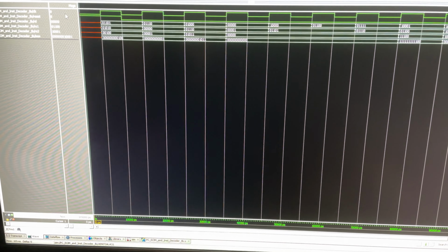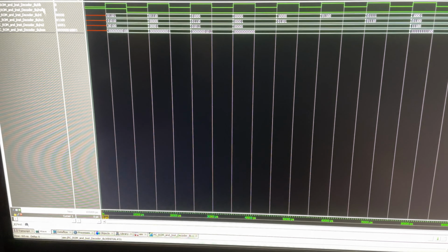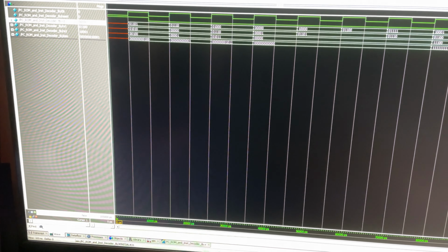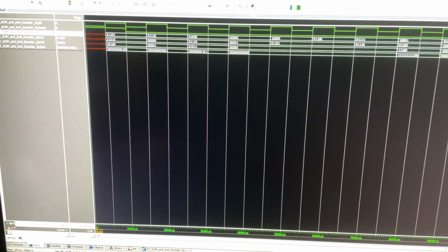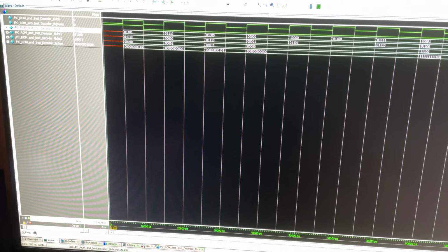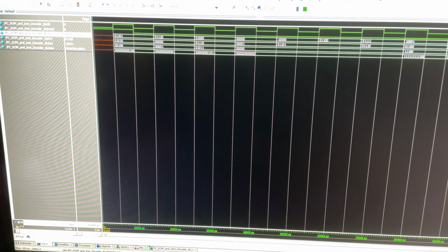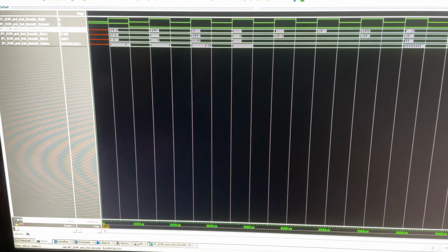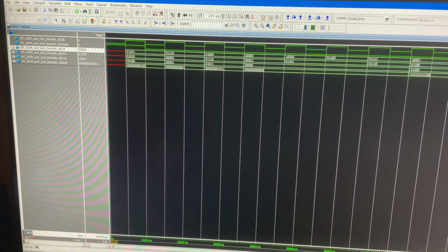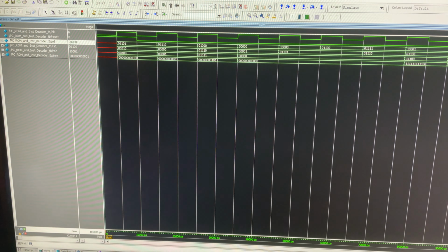The top 2 lines you see up here are the clock and the reset. These are going to go through and give us all of our values. And we got our outputs that we want to focus on right here, the bottom 4. So to talk about a little bit what happened with our test bench, we start off seeing if the reset input works, which it obviously does. The reset has to work to get the other values of the instruction address 0. Address 0 in the ROM is an add-I operation instruction, and it's going to add to A0 and put the result in A3. Then we turn the reset off.